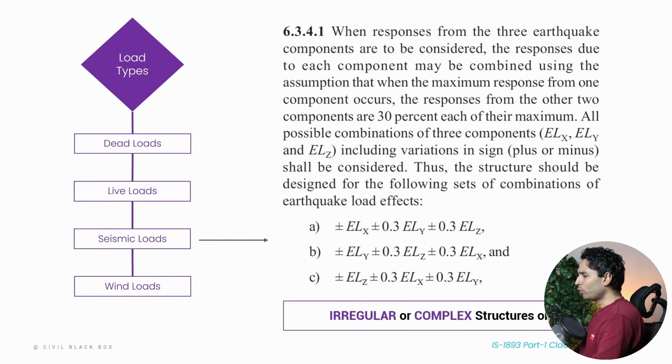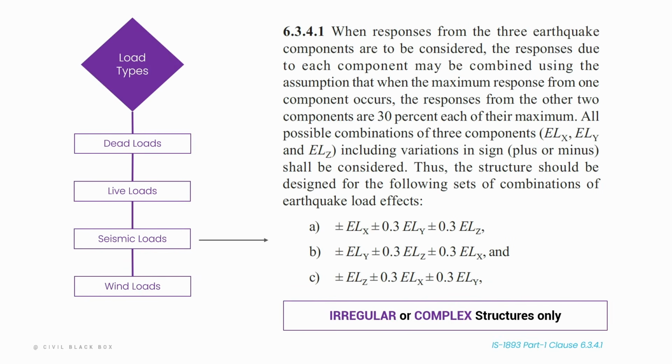Next up, one more important thing, which I'm not going to be mentioning in this video, but you should be understanding that when it comes to seismic loads, we usually work with horizontal directions of seismic loads. That is the earthquake load in the X direction as well as the earthquake load in the Z direction, considering both of these are the horizontal direction. And we do not work with earthquake in the Y direction or the vertical direction. We, however, need to work with the Y direction when it comes to irregular or complex structures. Since we usually work with regular structures, we do not go into it.